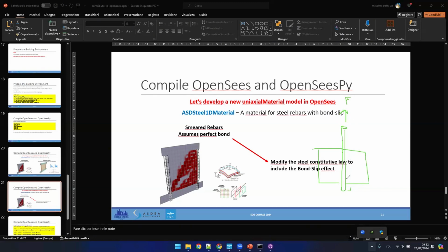And what happens inside the concrete is that due to the shape of the rebar and the aggregates in concrete, there is a transfer of shear stresses from concrete to the rebar, which has, more or less, a linear triangular distribution that little by little transfers stresses from the concrete to the rebar, okay? Up to a certain point, because at a certain point there will be slip, which means a creation of cracks inside the concrete, and the bar cannot carry any increasing load.